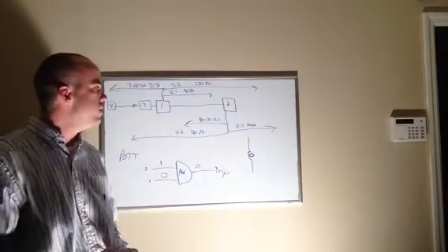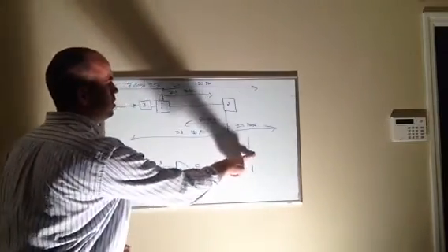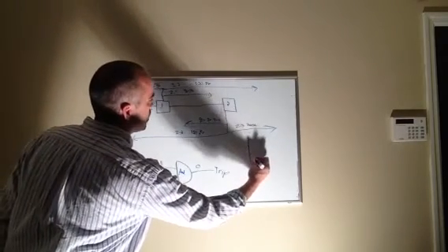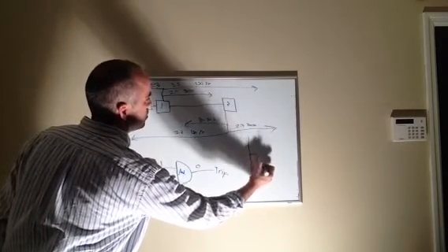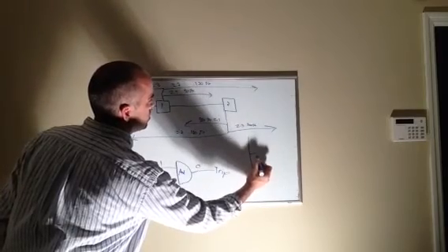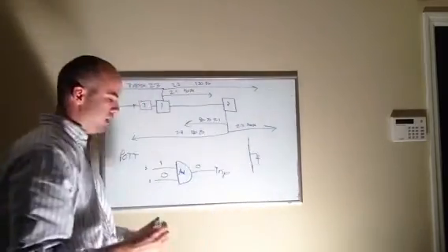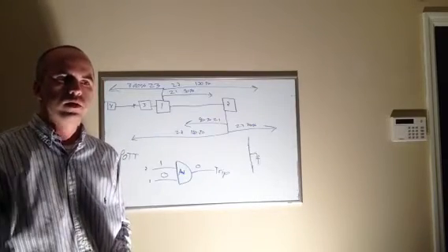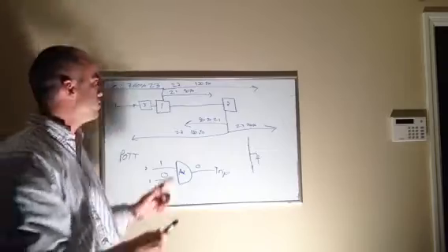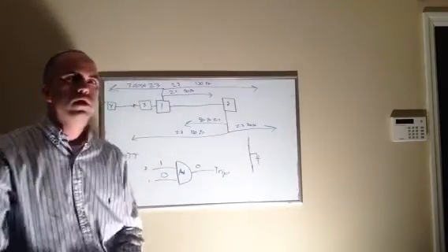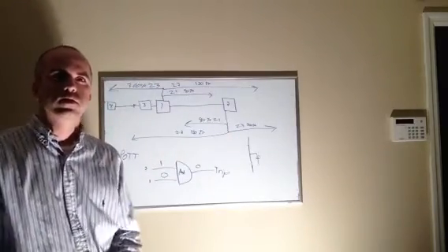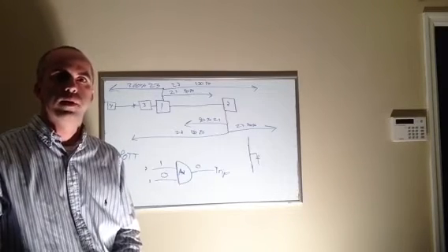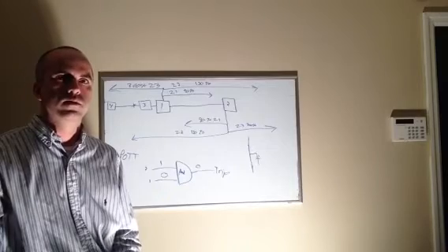And with POTT, you're probably not going to see a wave trap. You would probably see a CCVT on the line, some kind of capacitive device, and you might see a DPU, a digital processing unit, that sent communications back on fiber between substation 1 and substation 2. So those are some of the differences that you might see on a dispatcher single line, if you were looking to differentiate whether you had power line carrier or POTT.